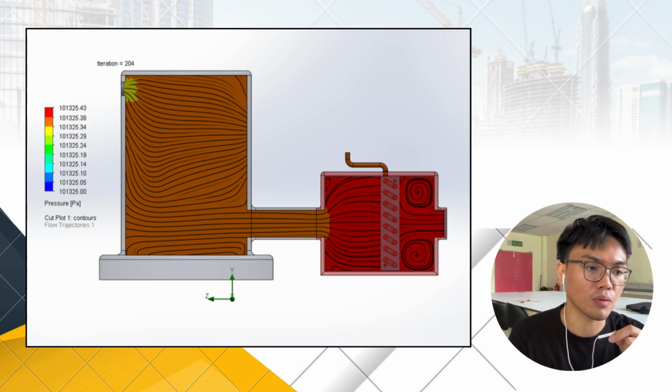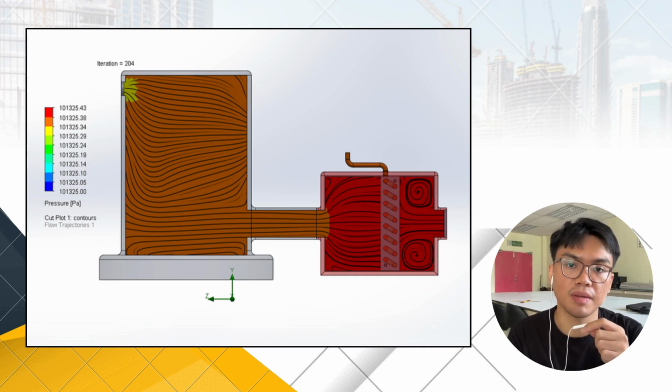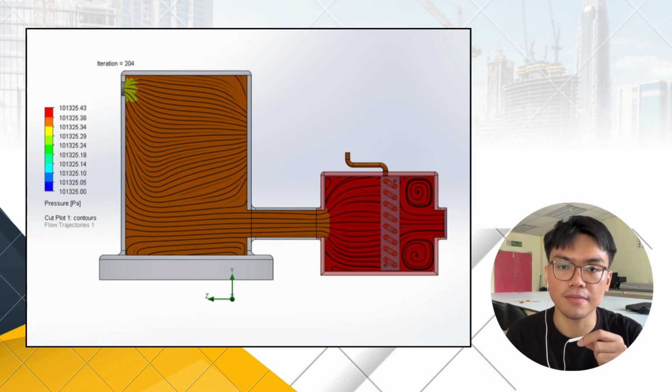From the scale, we can see in our simulation the pressure drops at around 0.43 pascals. This pressure drop is very small because the airflow rate is very low, around 0.00106 kilograms per second, based on our calculation, which we implemented into our flow simulation. The inlet velocity is only around 0.19 meters per second. Therefore, the system does not create major flow resistance, and the selected fan speed is sufficient to move air through the heat exchanger and the drying chamber uniformly, spreading uniform air temperature.